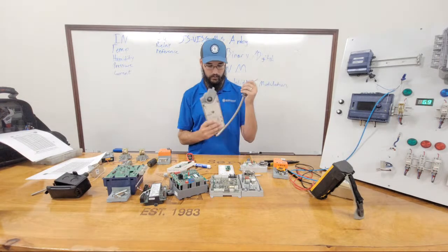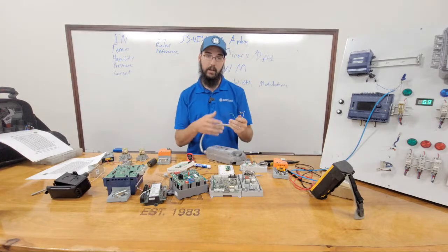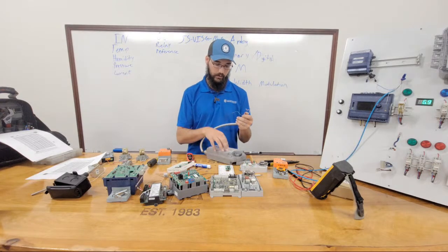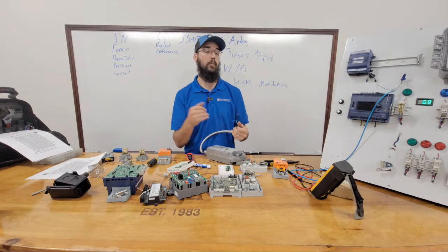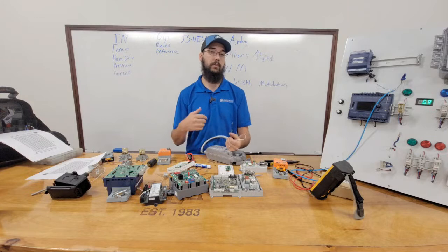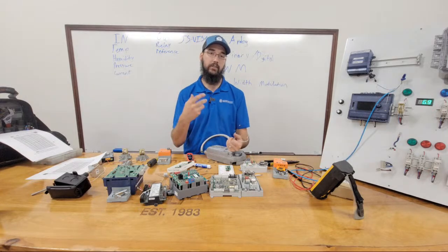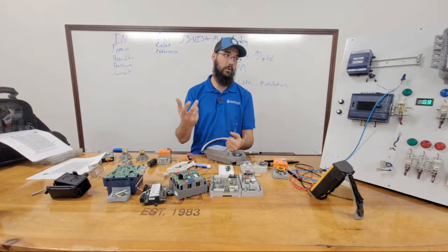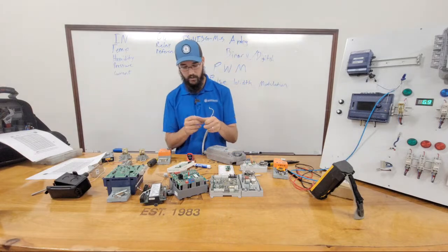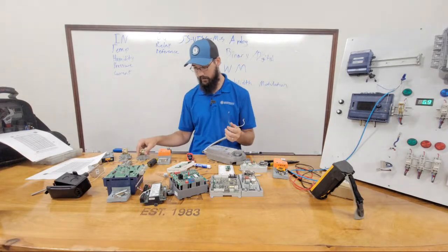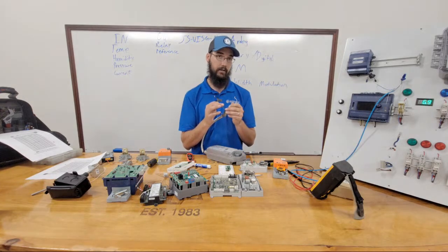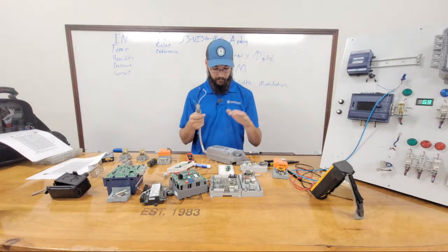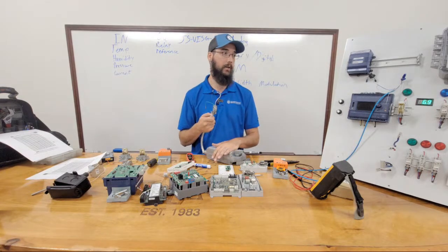So this could be hooked up to a contactor, and this could be controlling, say, an outside air damper that is just open or closed. So when the system is in occupied and is needing to run, and we need to pull in outside air, then the controller can fire the ISO relay, which then fires the control relay for this actuator, and we're able to open the outside air damper up and make it function for the mechanical room air handler.